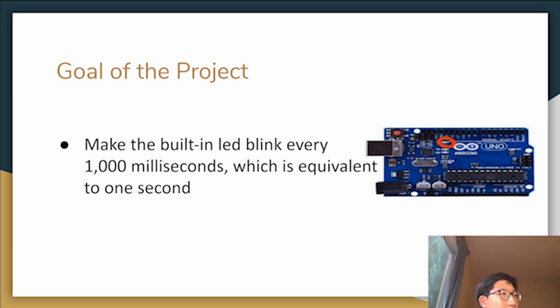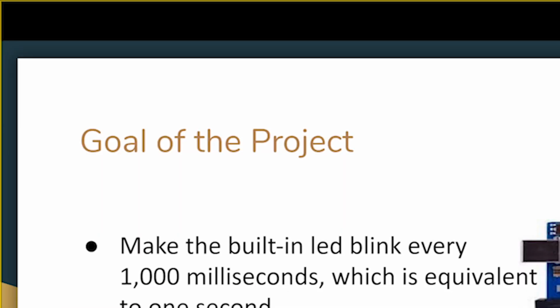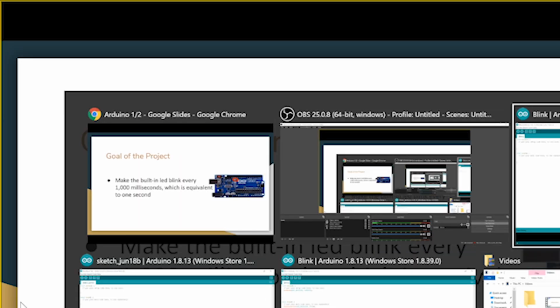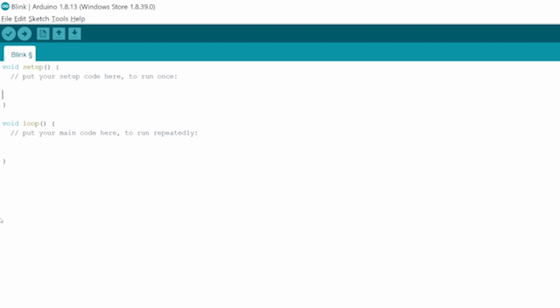Okay, now that I gave you 2 minutes, I will teach you the code. So you may be wondering what void setup is. Void setup is the function that runs once you press reset or power the board. It is also in the name: you set up the variable, such as I'm going to set this variable up as LED built in, because that is going to be our output.